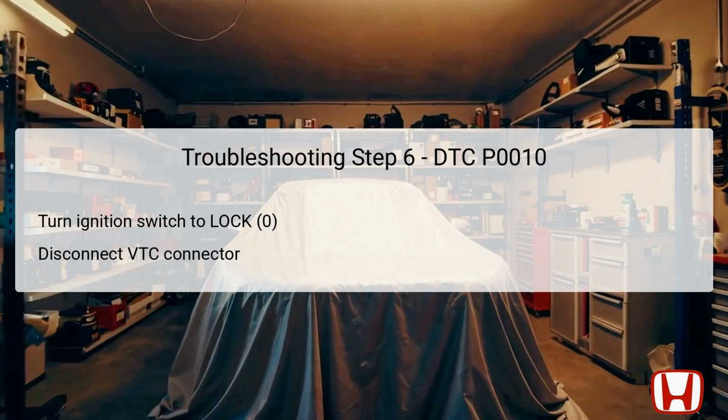By doing so, technicians can perform measurements and inspections more accurately. Proper disconnection of electrical connectors is vital to prevent accidental shorts or damage to the terminals or wiring. These foundational actions prepare the technician for subsequent steps that involve measuring resistance and continuity.